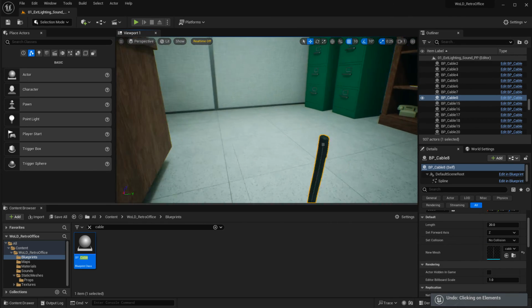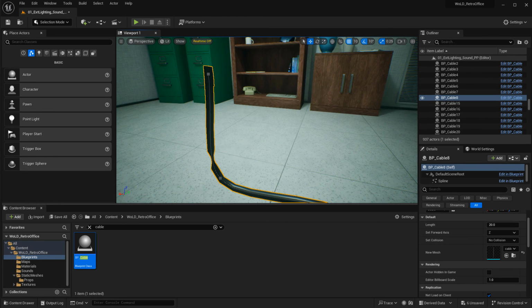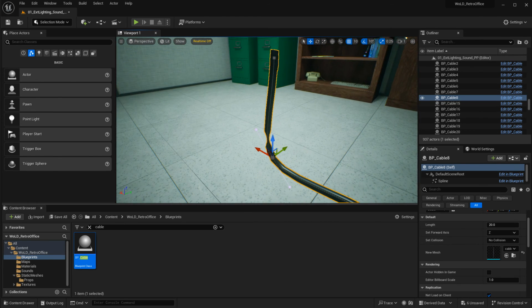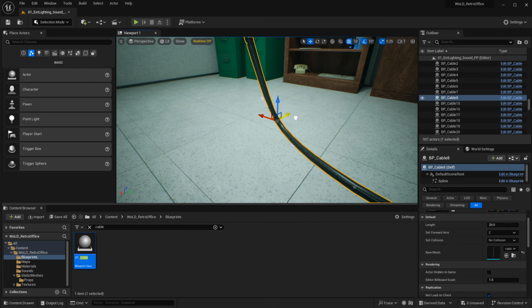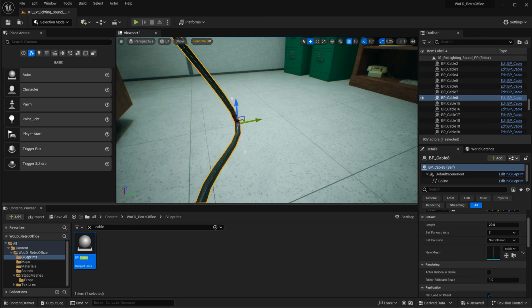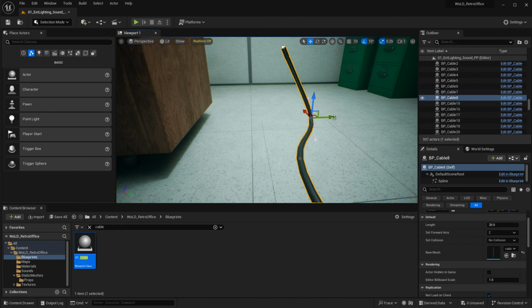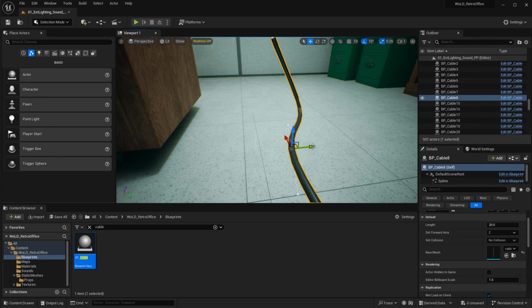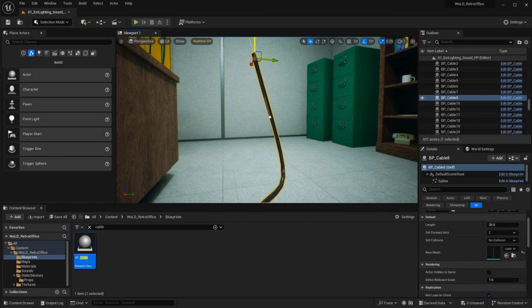There's going to be a problem at certain parts when you are creating spline points. It might start to bend your cable. So what you would need to do in this case, you can see that it's bending, is select one of the spline points near it, reposition it, and redrag the cable so it's not overlapping and not twisting over each other. You may want to disable the grid snapping so it's a little easier to manipulate. I already inserted the two spline points right here, and now you can control how this cable is run.